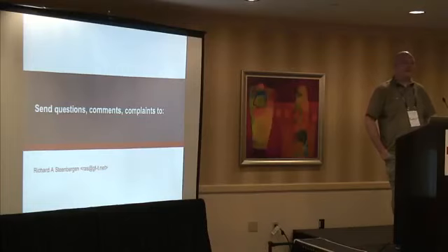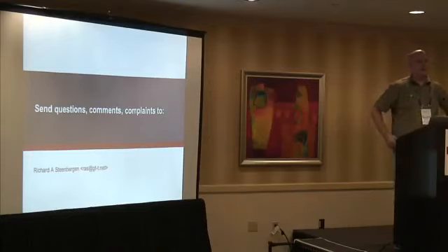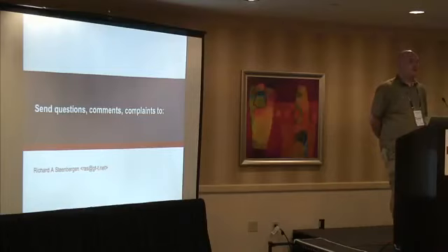You were talking at the start of the presentation a little bit about multimode fiber. I was wondering, how does it stack up compared to twin-ax cable these days? It seems to be becoming more and more popular. Not my area of expertise, but what people are working with on multimode right now is LRM, which is very popular. If you want any type of distance in the 200, 300 meter range, you're still going to need some type of fiber.